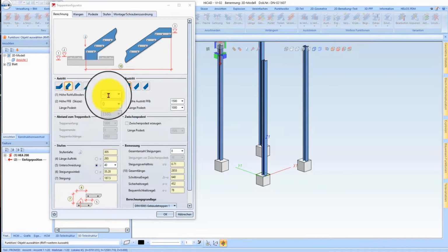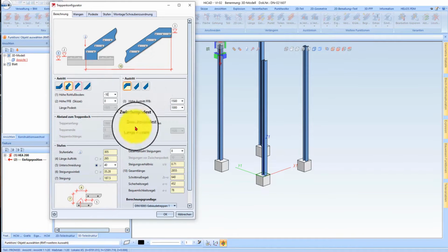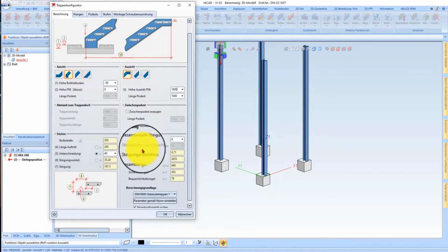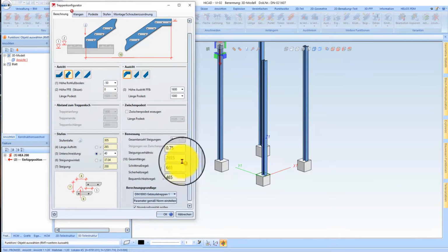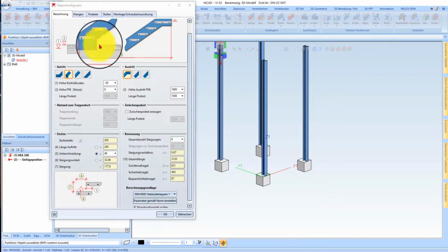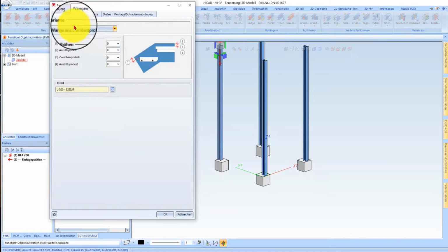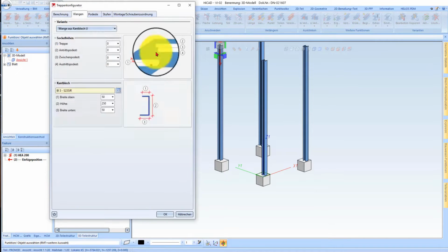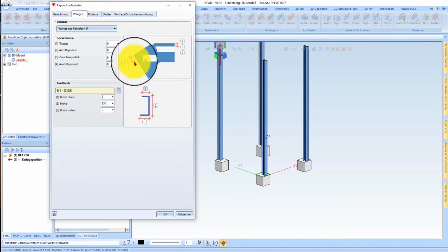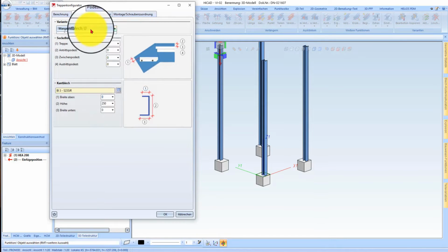So here I have the options to enter my values, meaning to input the floor structure that I know, the height of the staircase, which means I will just set it to 1600 for the staircase. When I click on it, you can see that certain values, for example, do not fit here. The step size is larger, and I can simply say that it should recalculate and adjust to my value. Of course, we also have the options to select the stringers here. Which stringers do I want? A U-shaped profile. Here, I could also go to 0.0. Now, an error message would appear during installation, but you can simply ignore it if you don't need it.